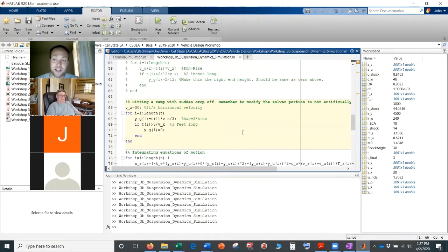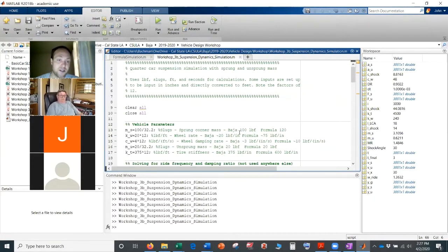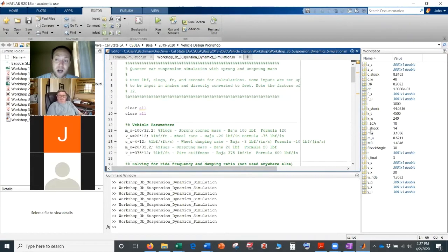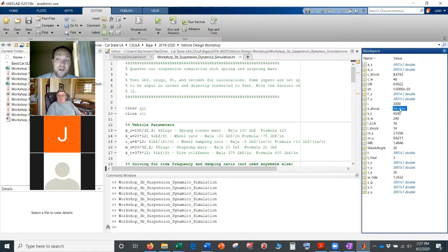And something like these quick calculations can help you figure out, okay, what should my shock stiffness be, right? So that you're not just buying random shocks off the shelf, right? This will get you in the ballpark before you do some testing, right? This is a model, it's not right, but it gives you some information to get you in the ballpark so you can start to tune around that value, basically.